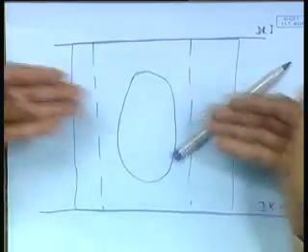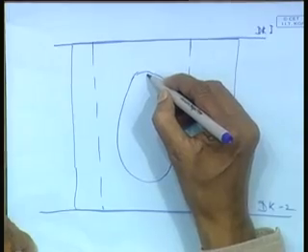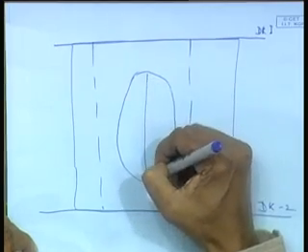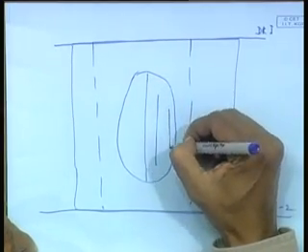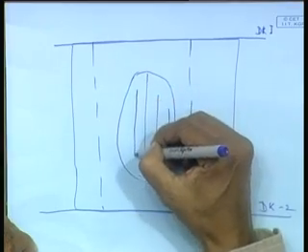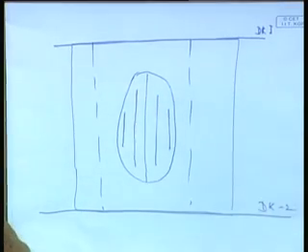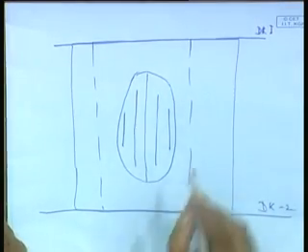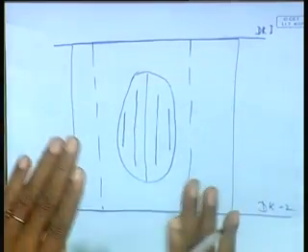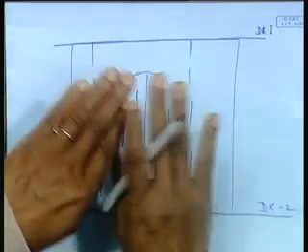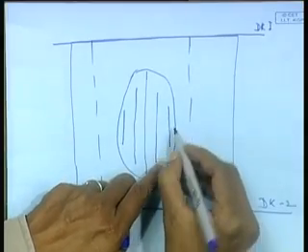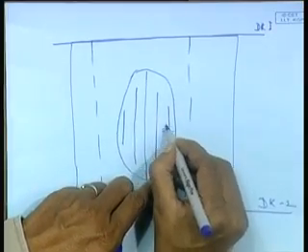So what you will do, you will have to do the shrinkage. So how do you do it? You give a heating line like this, then another line like this, gradually reducing. So this tries to bulge, to reduce the bulge, it shrinks. Along every line there is shrinkage taking place in this direction.